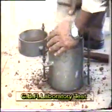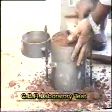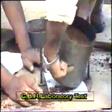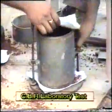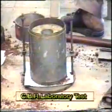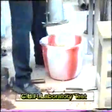3 such specimens are prepared and 3 samples are collected from each specimen for moisture content determination. The filter paper is now placed on the base plate and the mold is turned upside down. Filter paper is placed on the top of the mold along with the perforated plate with adjustable stem over the surface. Weight of 5 to 7.5 kg is placed.